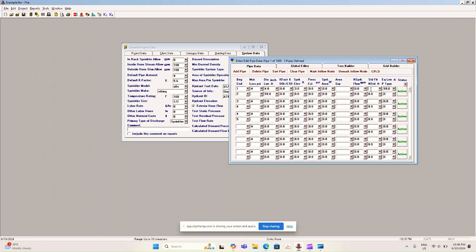And here comes the standard fittings, I suppose. If from node 1 to node 2 there is 1 gate valve, you just say 1 gate valve. And if you have 2 gate valves and 3 elbows, you specify that. So this is the way you specify the standard fittings from point 1 to 2. And so yes, that's it. Once you fill up all the information, you just have to click this button, which is called calculation.